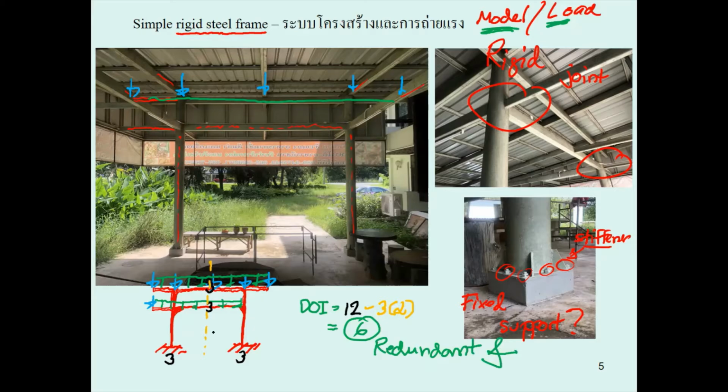And then do we analyze it by using the displacement method? Yep, you can solve it by the displacement method, but you will consider that under the application of this force, you may have the sideway on the second floor, and you have the sideway on the third floor.